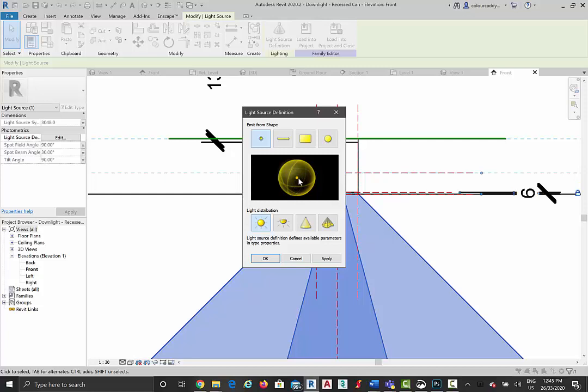So the way you work with those material-based lights, which is called object-based lighting, is that you use them as supplementary lights. You still need to have some lighting families to provide most of your light, and then you add extra glowing materials and other secondary light sources with a material. They do act as a light source, so they will light up other things, but not as well as a light family. I'll try and give you some examples on that if I get time at the end. But good to think about that too.